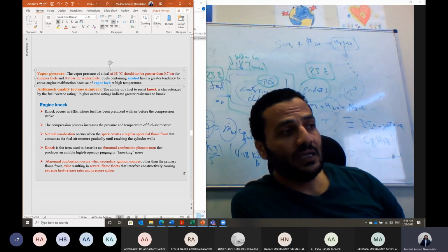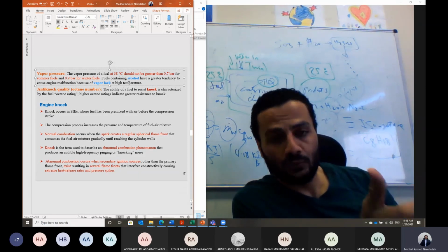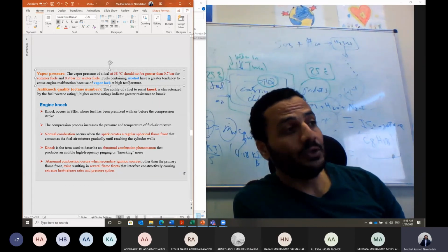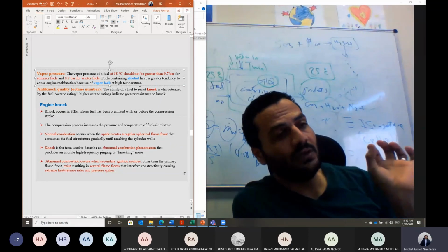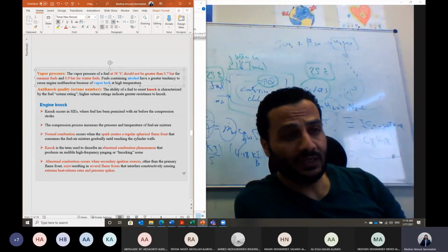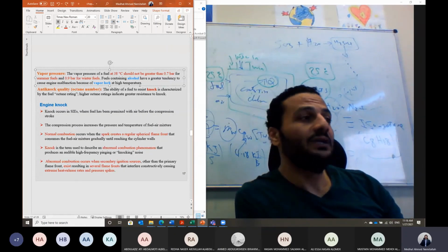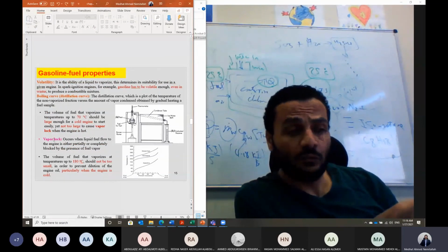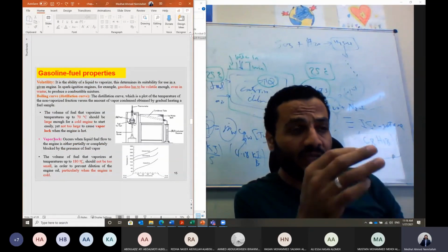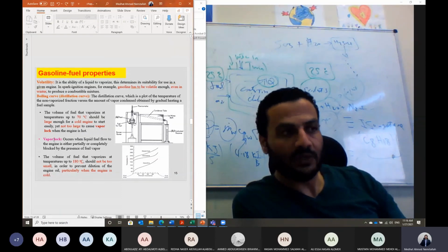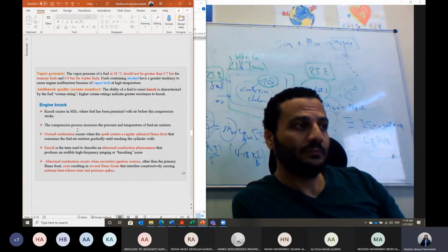Okay. Usually they have some alcohol fuel added to the gasoline fuel in order to improve its performance and its octane number. We can add some alcohol, but usually using alcohol is not preferred at the engine startup, because this alcohol will be vaporized in significant amount and it will cause what we call vapor lock, where the fuel will be vaporized in the fuel line and it will block the fuel line once the engine heats up. Okay, is that clear, guys?